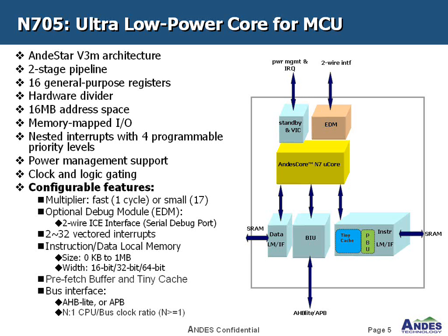For the debug module, N7 can choose a two-wire interface. The two-wire interface is mini JTAG. Standard JTAG is 5-wire and mini JTAG is 2-wire, so it can reduce the pin count in your chip. N7 can choose at most 32 interrupt sources. It means N7 has an interrupt controller inside, so you don't need an external interrupt controller.